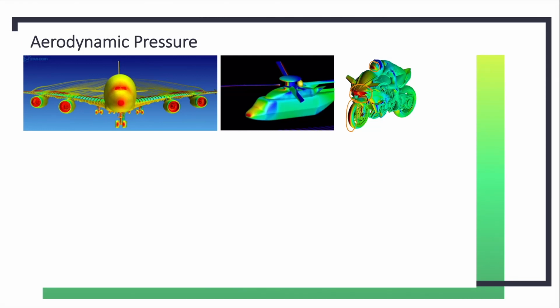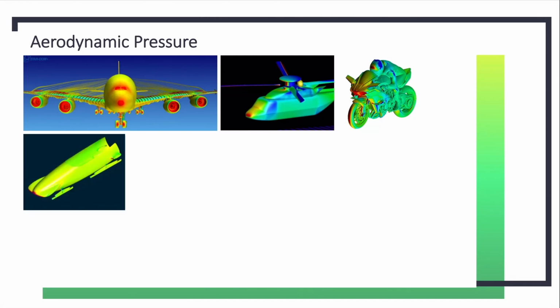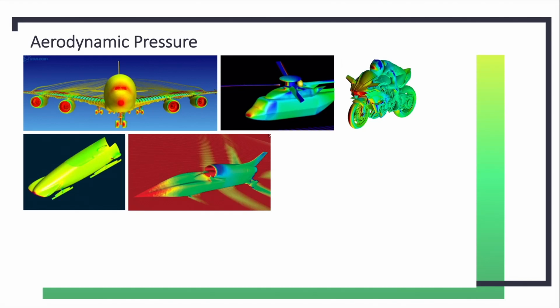This is an example of a bobsled, exactly the same. Now, bobsleds are designed for low drag, so we can see we've got a very, very small amount right at the front. And this is the sort of thing that we want to do when we start looking at our Greenpower cars. This is an example of the Bloodhound. Now, the Bloodhound has quite a large pressure area at the front, but it goes quite nicely into a green region, and that's quite a neutral pressure region. Areas that are blue, like the top up here, that's probably where we'll see flow separation.